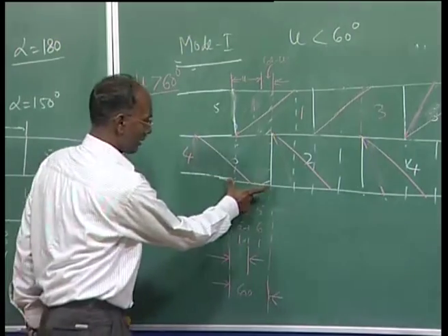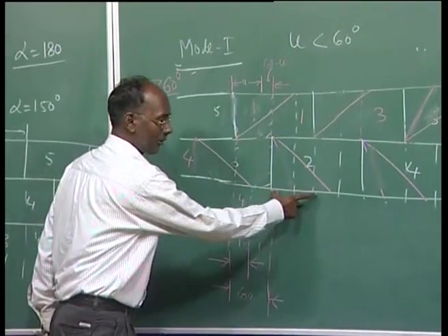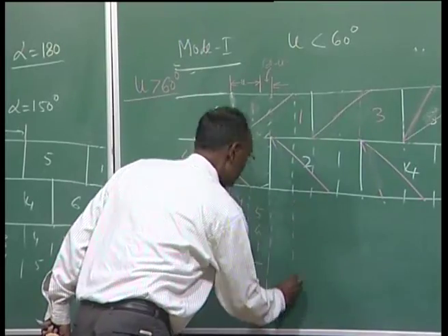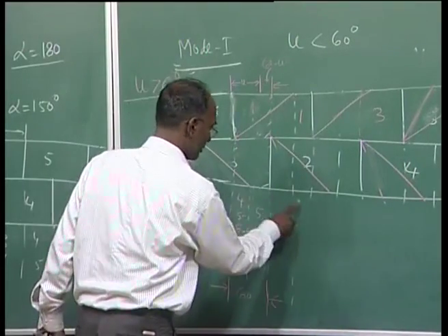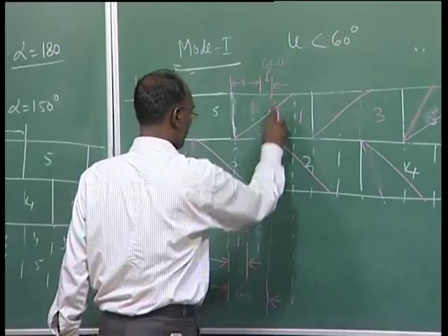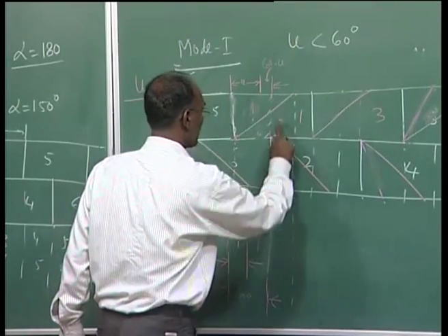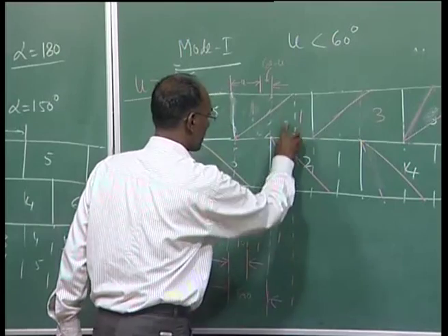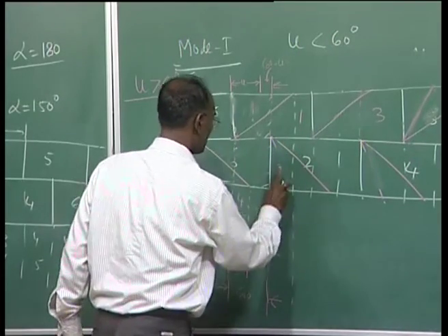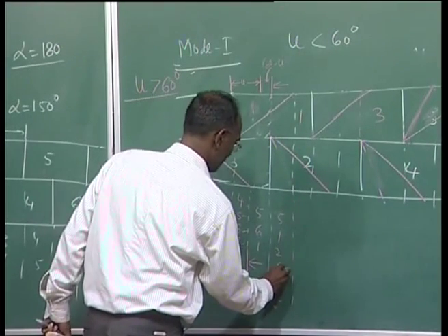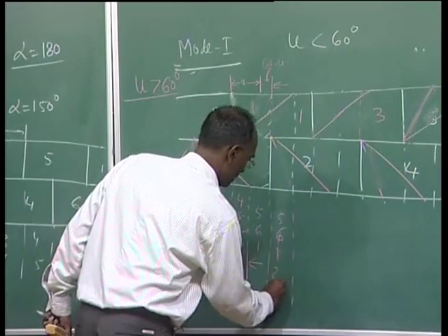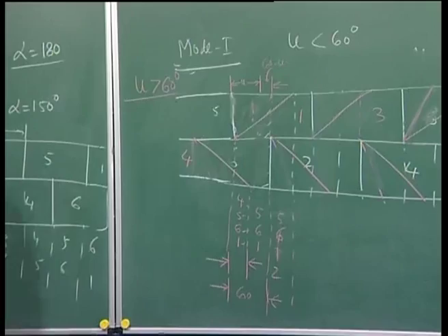This period here is 60 degrees, this is another 60 degrees. Now I am going to write again from here to here. Now you will find 5, this is 1, right, 2 here, 6. So I can write here 6, 1, 2. So it is 4 valve conduction. So this sequence will follow.